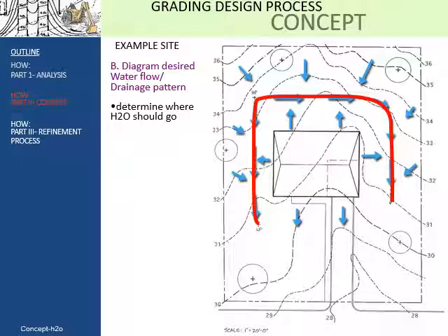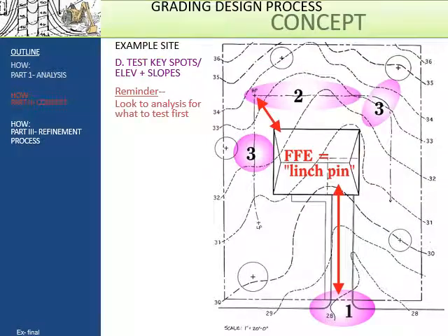and that's how you're going to start this process. And then what you're going to do after you get that swale sketched in, and you understand the basic ideas, is you're going to have to go down to the road and you're going to have to see about how we're going to make a connection to the road. Because that road is one of the determining factors for the finished floor elevation of your building. And frankly, this finished floor elevation becomes the linchpin for your entire design.